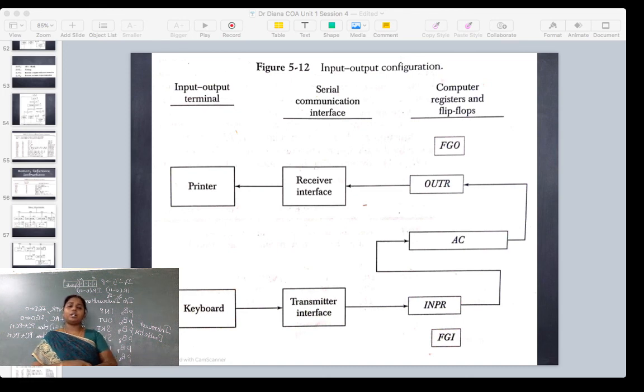When the input device is trying to send something to the CPU, if the interrupts are not enabled by the CPU, the interface will keep that data with itself and be ready until the enable flag is switched on. When the enable flag is switched on, it immediately sends an interrupt request to the CPU so that the CPU can now start reading data from it. So this is how an interrupt system works.